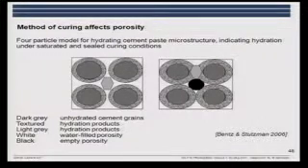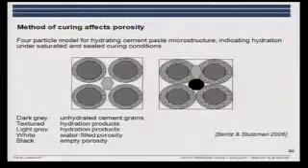There's another thing you need to consider if you want to make samples and you want to have a given structure. This is work by Dale Bentz and Paul Stutzman from NIST, and they were working with the impact of curing, the amount of water available during curing, on the pore structure. And they came up with this schematic graph showing here we have cement grain unhydrated, hydrated, we have water, and then we have some reaction products.